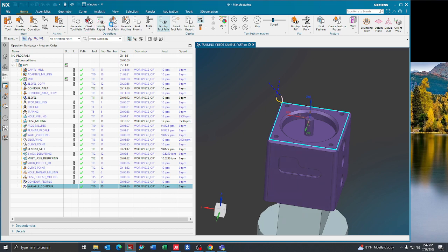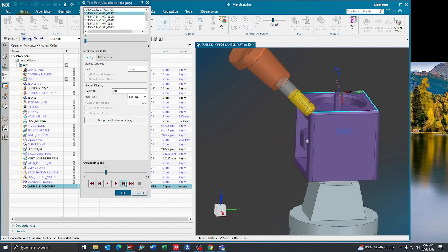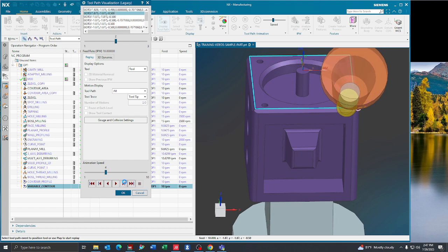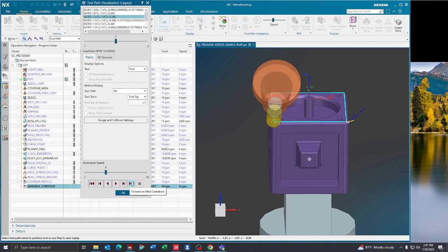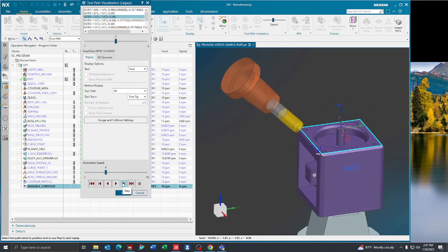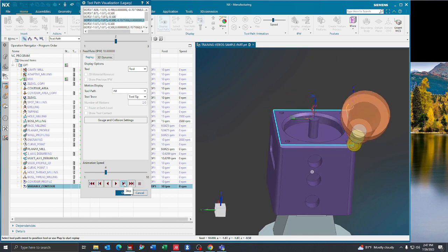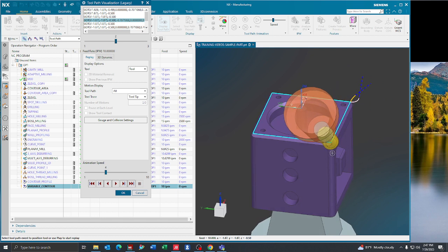Here you can see that we now have a toolpath that comes in normal to our chamfer and is going to cut just around this chamfer. Now when we get to here, you'll notice it's going to do a big tilt like that. That's what happens when you use that tool axis normal to part. So depending on the travel limits or the type of machine that you're in, that may not be an option for you. You may have to break this up into 4 separate angles.